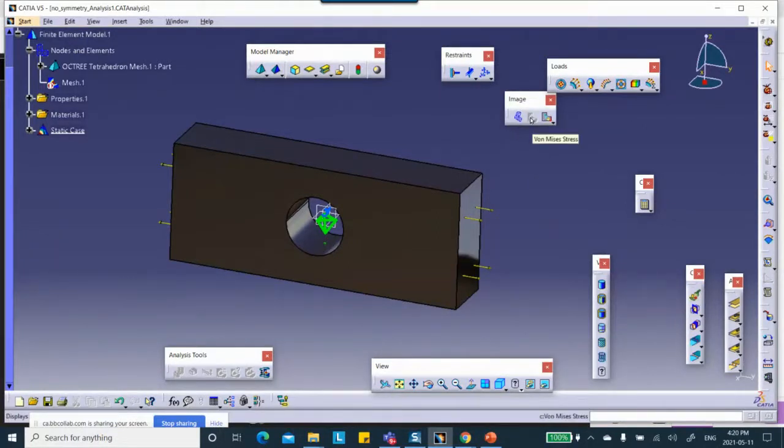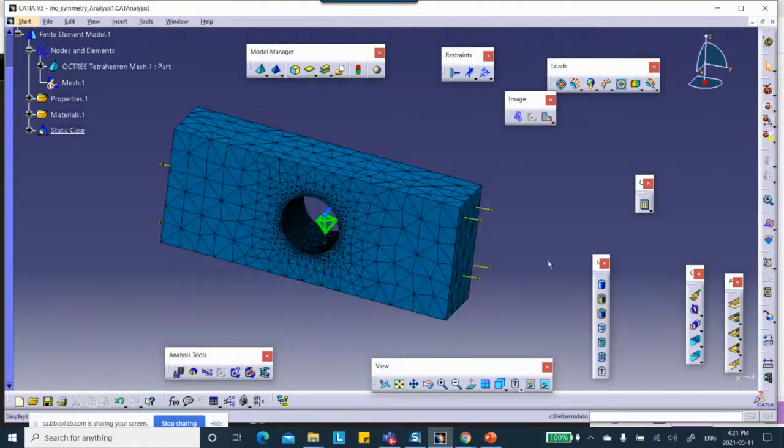Notice that we cannot plot the stress for a good reason, because they don't want an engineer to get to this point. It is wrong because it didn't run, but look at the stress, and that stress is garbage. So they won't let you plot the stress, because it didn't actually run. But I can plot the deformation and plot the displacement. Displacements are rich. It's going to be 10 miles or something like that. But the deformation right there, and you can animate it.